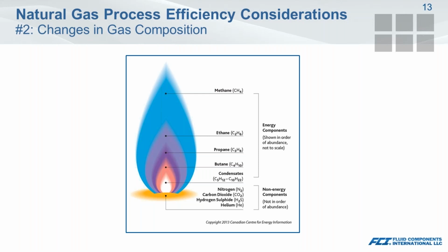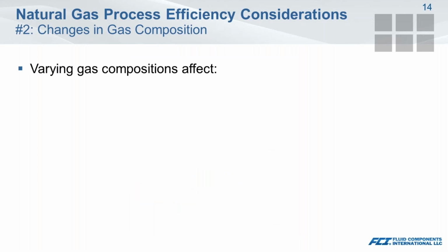For an accurate flow measurement, the actual natural gas composition is an important consideration to select and calibrate the natural gas flow meter. These differences in composition will also impact the calorific value of the fuel being burned. By properly addressing these variances, we can ensure that our flow measurement is optimized and maintain the appropriate air to natural gas ratio.